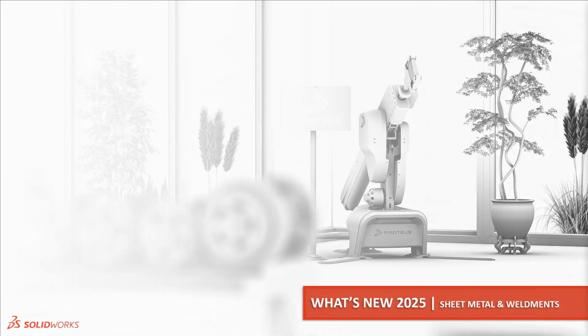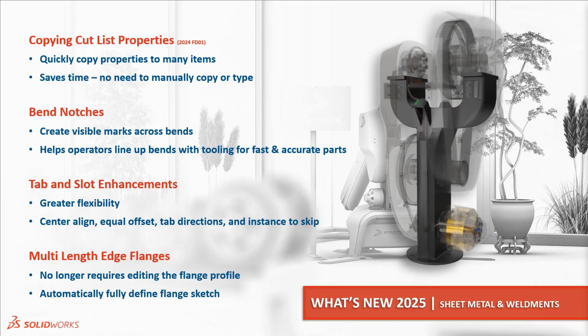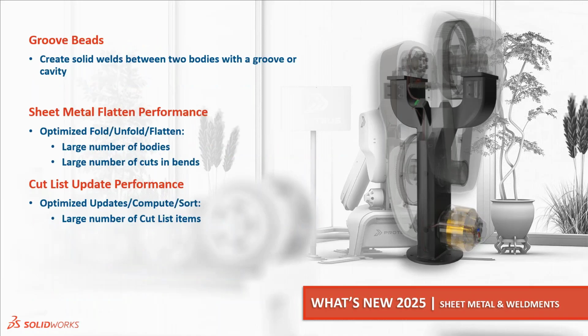We move to the next thing, the new announcements in sheet metals and weldments. In the latest version of SOLIDWORKS software, we can copy cutlist properties. We have the option of bend notches. There are key announcements in the tab and slot command, and we have the option of multi-length edge planes. If we create two edge planes at a time on a few edges, we can use multi-length. I will show you when we move to the video of that one. We can also create a solid between the bodies.